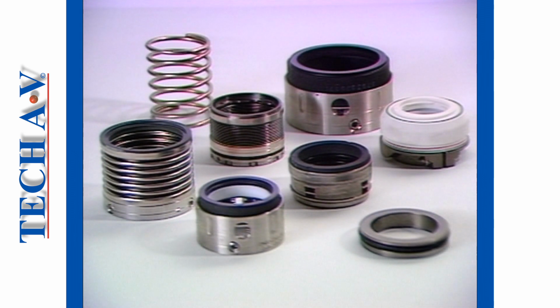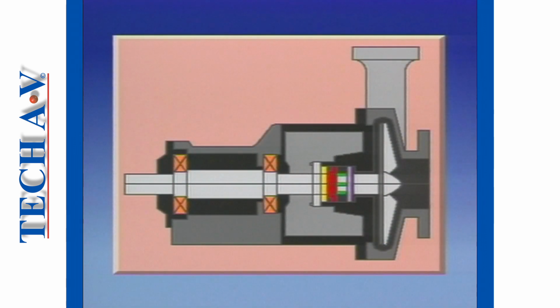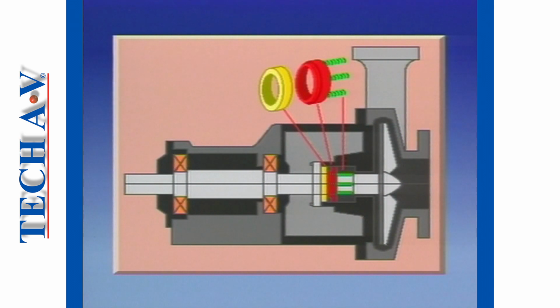The devices subsequently developed, and which are extremely effective in achieving the desired leak-free effects, are today known as mechanical seals. In principle, a mechanical seal comprises a primary seal of two flat polished rings that rub against one another. One ring is kept fixed or stationary, whilst the other rotates, usually driven by the shaft. Face-to-face contact between the primary seal face and the seat is maintained with a spring, or a series of springs.